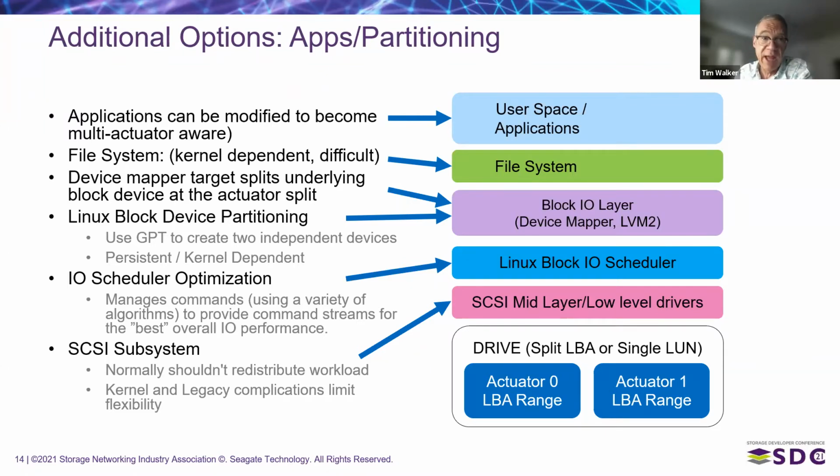And then below that, we have the case where the scheduler comes into play. The scheduler naturally reorders the commands and groups them for efficient operation. Schedulers designed for single target, single actuator devices will not necessarily reorder or stage the commands in the most optimal sequence.